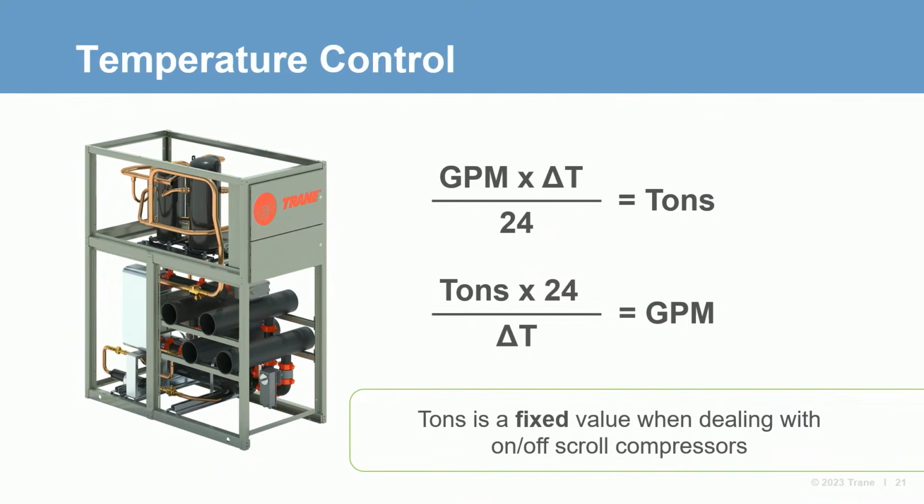We already showed how if only 1 compressor is running, you have half the tonnage and therefore half the delta T. Now let's focus on how flow affects our modular chiller performance. Remember, this equation applies to each module individually, as each module is a chiller in itself. This equation also means that anytime you vary flow to a module, you are changing the delta T.